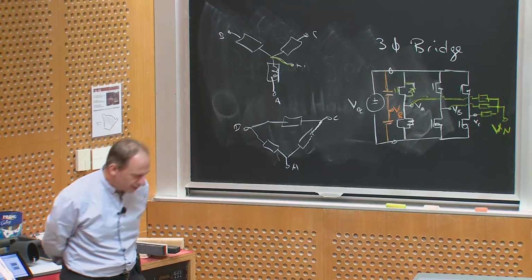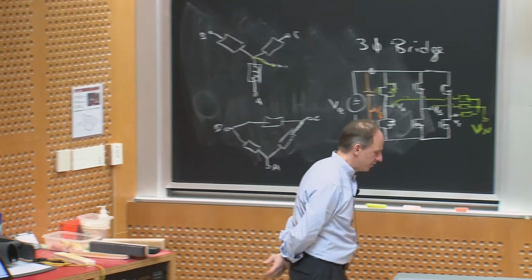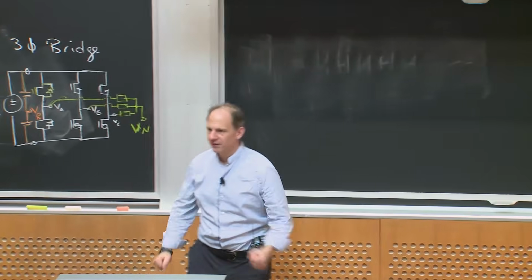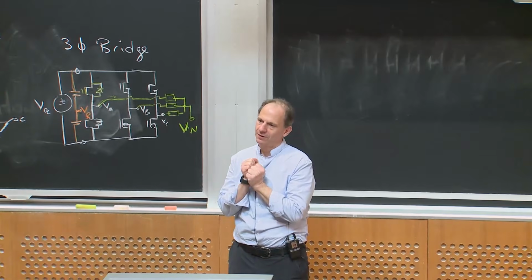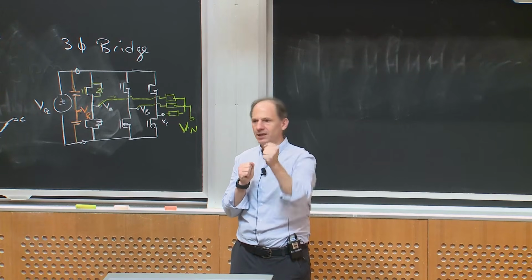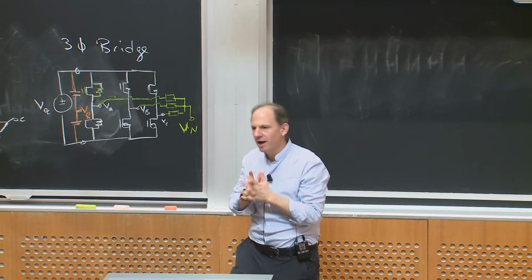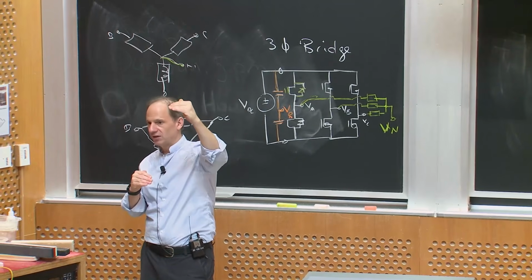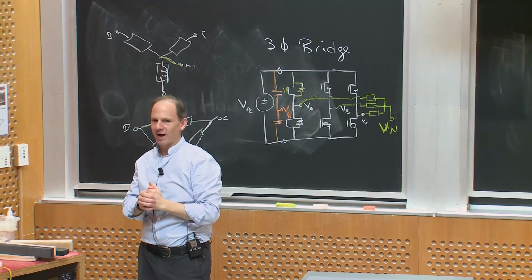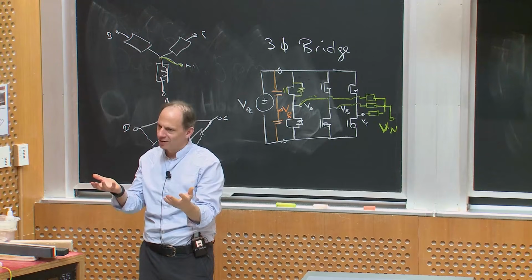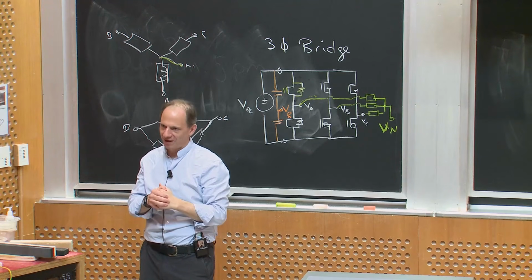Ah, that's a very good question, because if you think about it, a MOSFET's on state looks like a resistance, whereas an IGBT's on state looks like a constant drop. And it turns out that at the time that was built, for a very high voltage device, you could get lower forward drop for a given device area with an IGBT than you could with a FET.